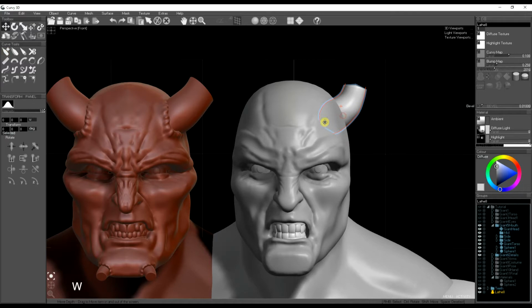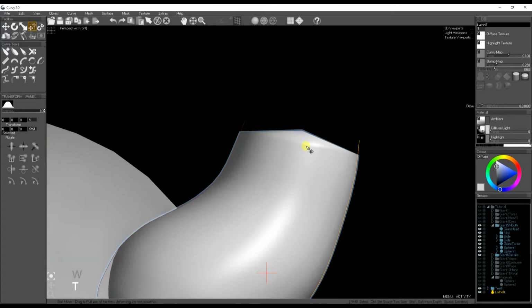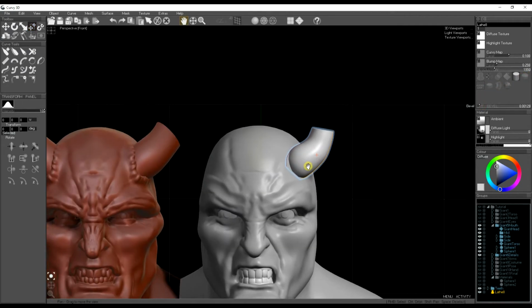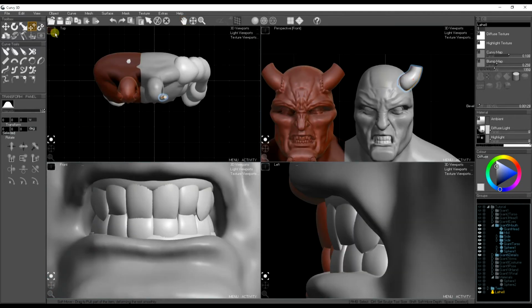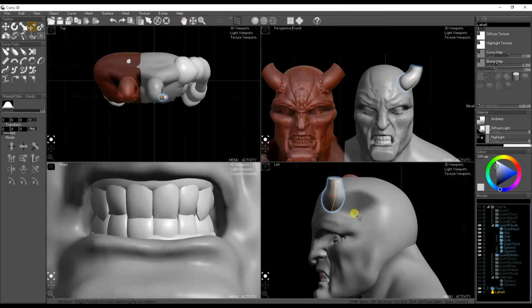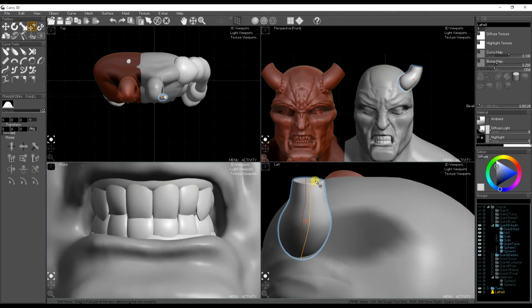This gives us a lot of control over the shape. Then with the move tool, I'm holding shift and dragging it in and out of the screen. Notice at the top where the curves are spaced out, it flattens off the end of the shape, but we can flatten it off more by turning off the smooth curved cap and reducing the bevel to a tight edge.